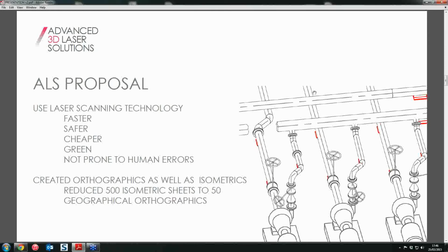We actually use mostly reference spheres out on these sites, mostly because the sphere can be scanned from 360 degrees. We've found that checkable targets are limited to a certain range, and you can only view them at a 45-degree angle, or no more than a 45-degree angle.